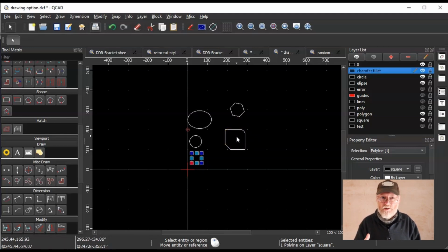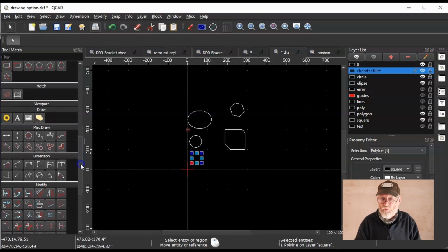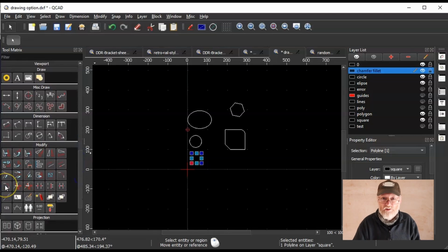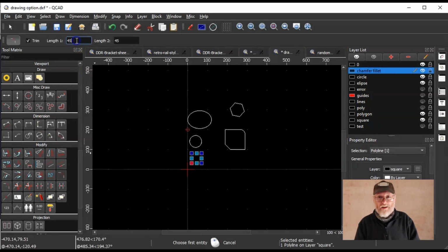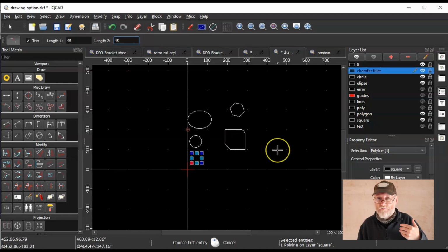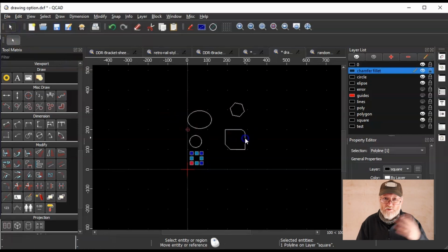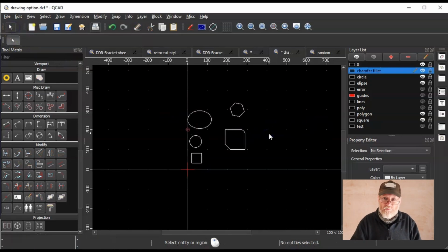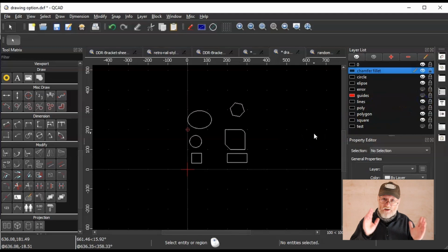And for this I always say that you should be using geometric shapes as much as possible. Most CAD packages have within them a list of different fixed shapes that you can use. If you need a square, pick a square. If you need a circle, pick a circle. If you need a polygon, choose a polygon. Same goes if you need to edit a part to add, for example, a chamfer or a fillet to a corner. Don't use lines, don't use circles and edit it out. Look for the chamfer tool or the fillet tool and use the parameters within that to create the object.